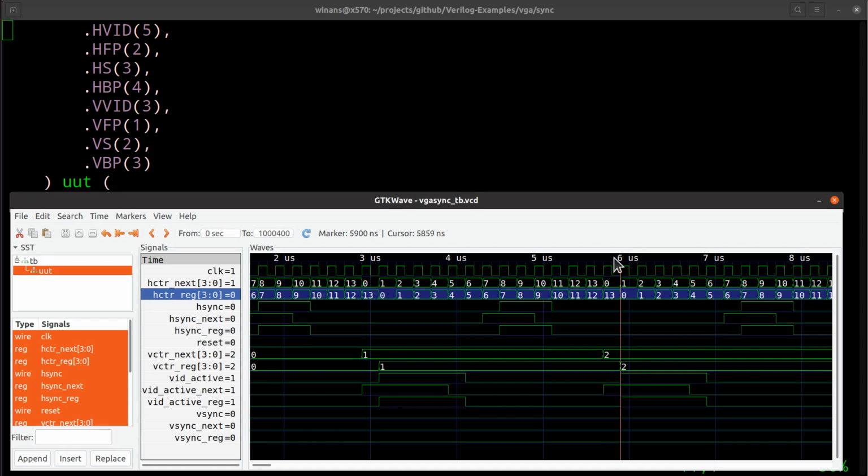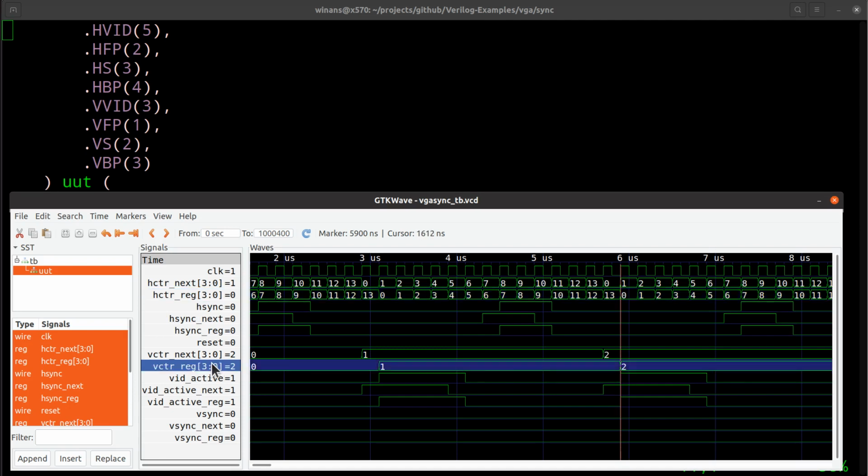Video goes active again. You also see in here that the vertical row number has advanced at that exact same time as this thing moves from the max over to 0. That's when this is supposed to advance. You can see the next thing getting ready and saying the next one shall be 2 on the next leading edge clock that comes by.